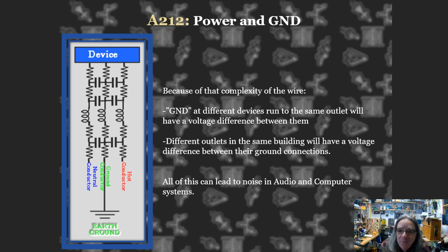That might be a couple hundred feet. It'd be a really long power cable. So there's a big voltage difference then, big as in a volt or two, between earth at the stage, where everything else is plugged in, your power amplifiers, speakers, musical instruments, and the console, earth out there.